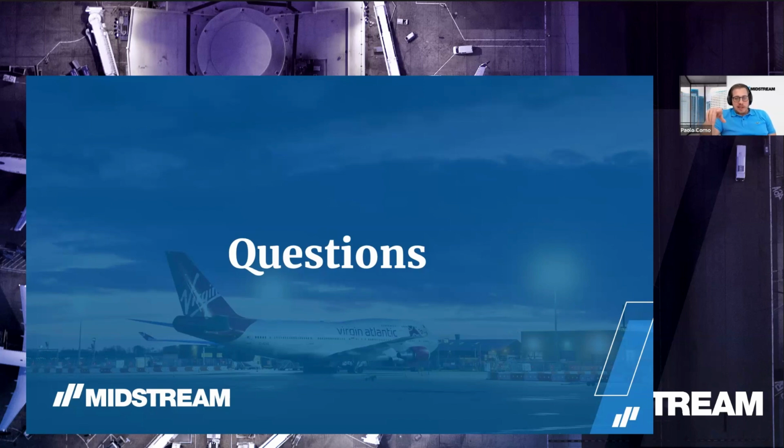The data you need to look for in the data sheet are the data coming from TM21 projections, so the L90 B10, L80 B20, and those types of lifetime data. Okay, brilliant, thank you. So yeah, we'll follow up with that one. Our next question, thank you everyone, we've got so many. We'll try and get through what we can in the next 5 minutes.